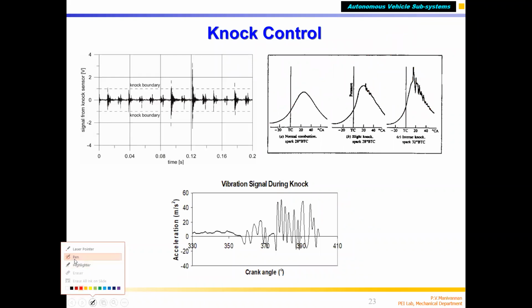What happens is that this pressure wave will rattle the cylinder and piston. The engine's main part is the cylinder, and it is moving violently. When it moves violently, stresses develop in the cylinder, and the cylinder can break. The engine itself can break if you operate under this. Apart from that, it will make a violent noise.